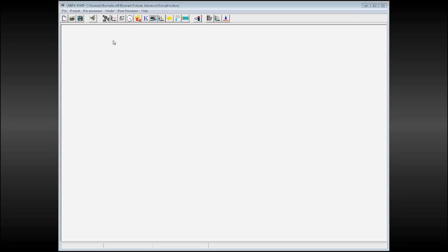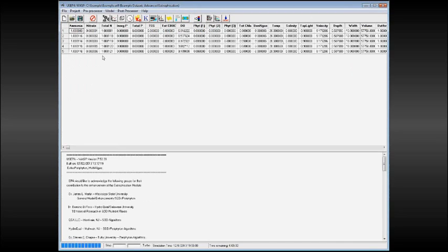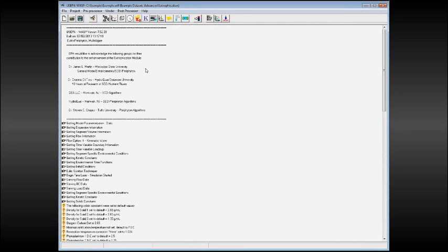Okay, with the file saved now, we can go ahead and run our example input file. To do that, we're going to click on the icon that looks like a WASP, and it executes the model. And what happens is, when you hit that run button, it loads the appropriate model type. In our case here, this was the eutrophication and multi-algae model, the advanced eutrophication model. And as it's running, it displays information to the screen.